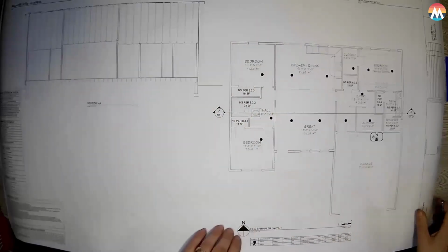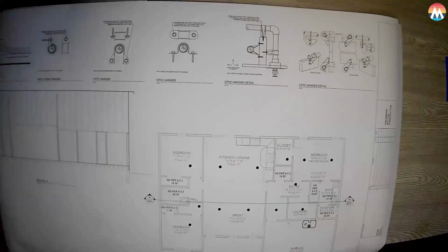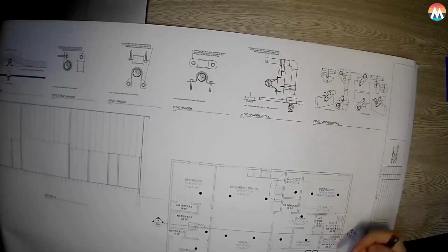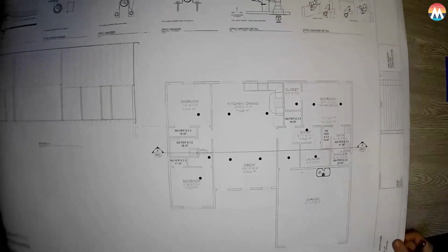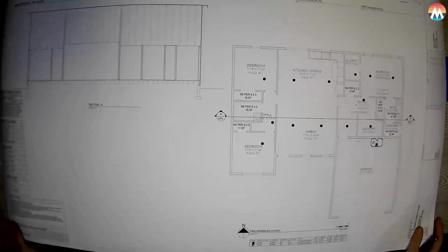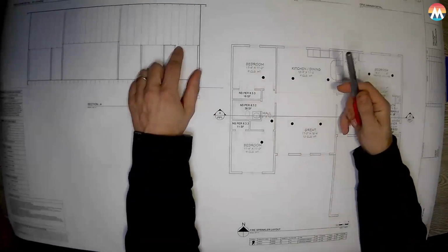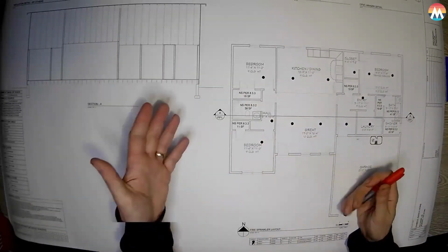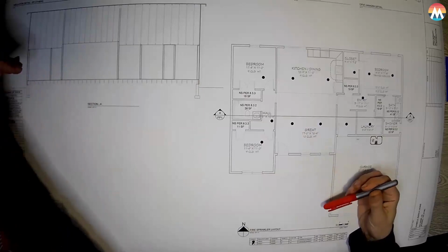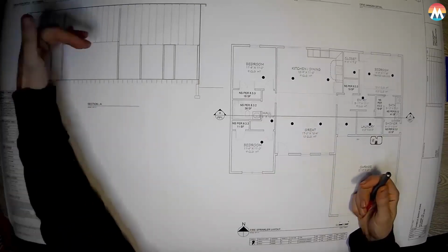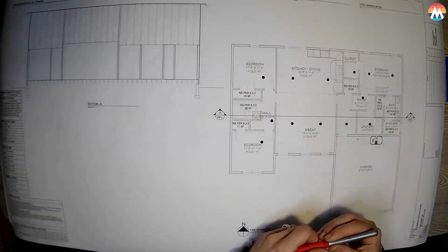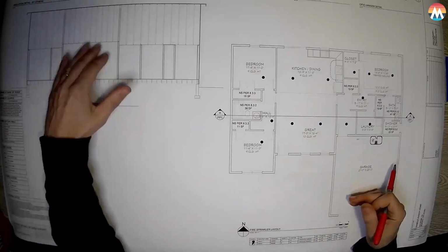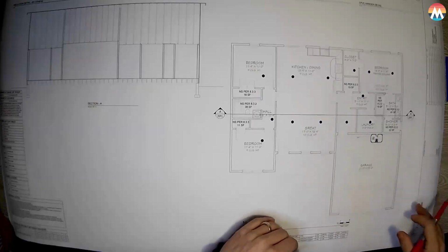To resolve that, I don't know if you guys can see this or not, but these days they invented this double offset hanger that resolves that problem, and so we no longer need the 2x4s to lay across. But anyway, it still is just good practice to, for the most part, run perpendicular to these manufactured roof trusses and lay right on the top of those bottom chords.